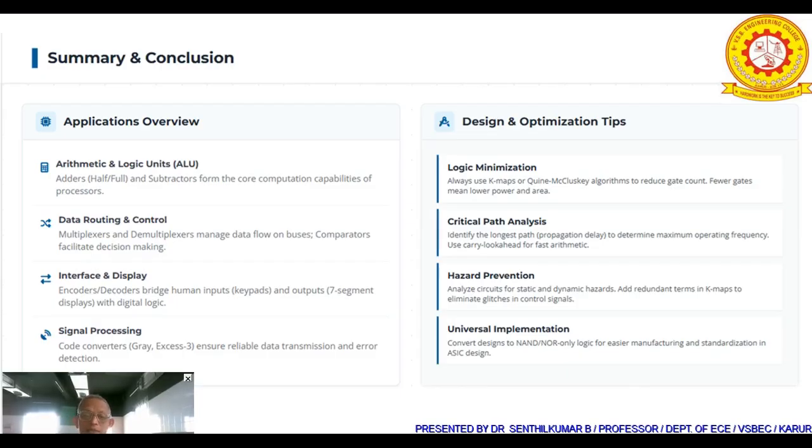This is the major requirement in designing digital logic circuits. We have to give much importance to it while designing any kind of combinational circuit. Next, we should have a critical path analysis. The propagation delay is the major issue if any path conflict arises. Path means where the data flow is happening between the input and output. We have to have an effective mechanism to avoid complexity in the path flow or data flow in the designed path.